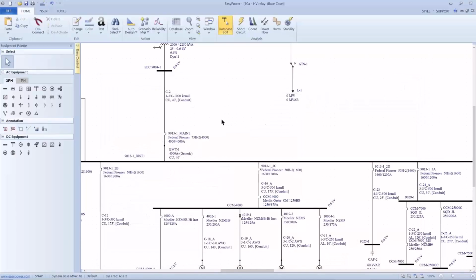In fact, that's the way some data collection is done by some people. They just go through and take pictures of each element with annotations about the main on that particular bus and then the feeders. And they have a system that they can tell by their notes and the pictures that were taken, that the nameplates on each of the elements show how to draw the one-line diagram once they get back to the office.